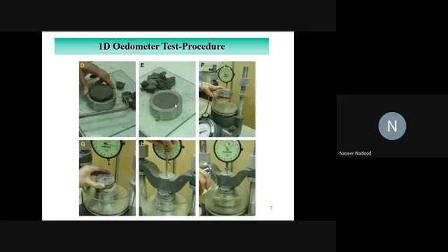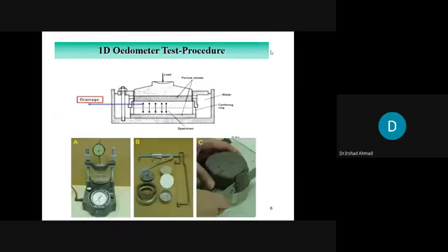Sir, so that there is no lateral deflection. Yes, so that the consolidation or any compression occurs just in the vertical direction. Achha. What is the purpose of sandwiching this specimen in porous stones, up and below?